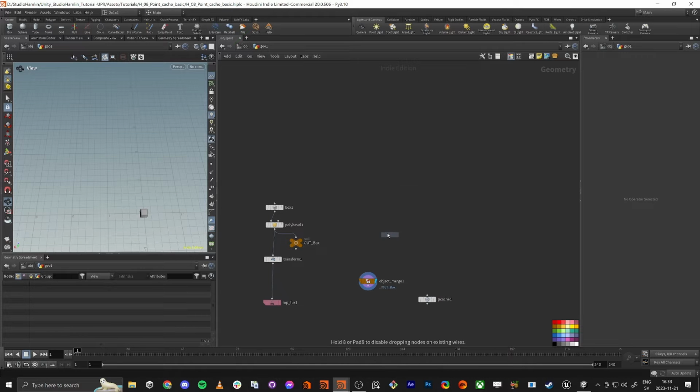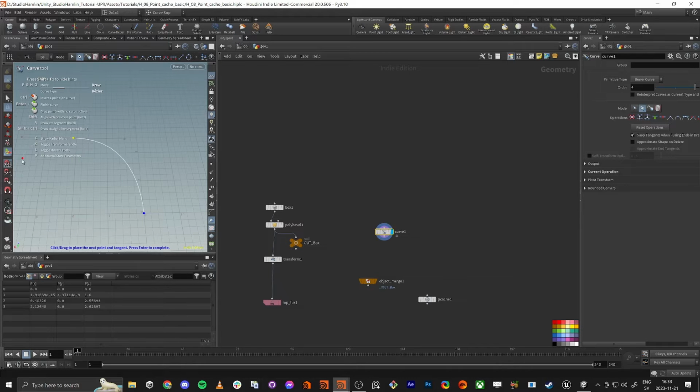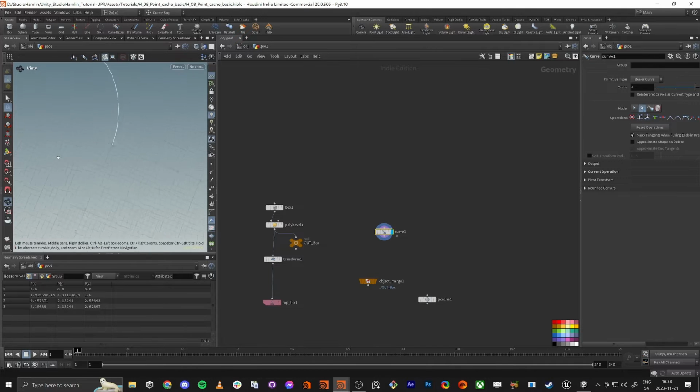Curve Bezier. And we're also going to tick this on the grid, so we snap it to the grid, and press enter in here. Then we're going to draw it. I hold and drag, and I hold and drag. And then I'm going to release this button here and press enter. And now I'm actually going to lift it up. So I hold the middle mouse button and lift it up. So I have this curve here, right?